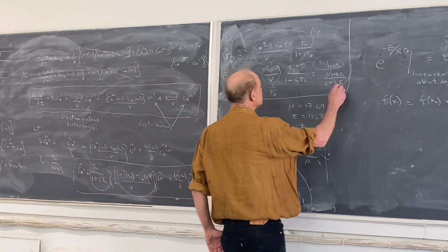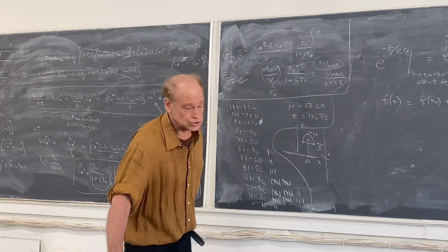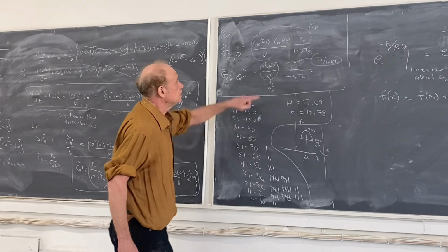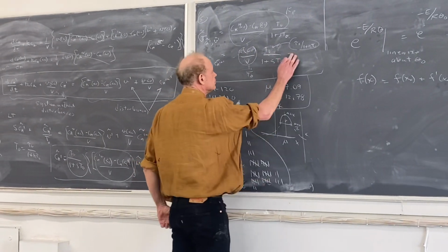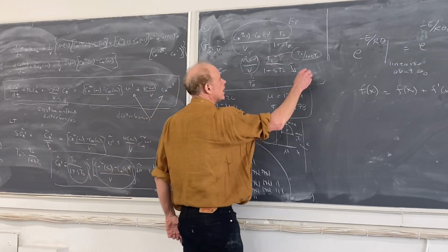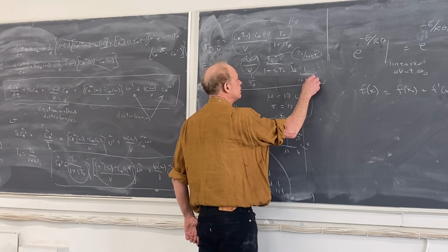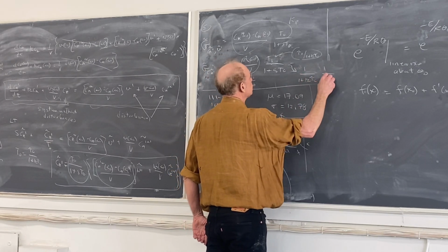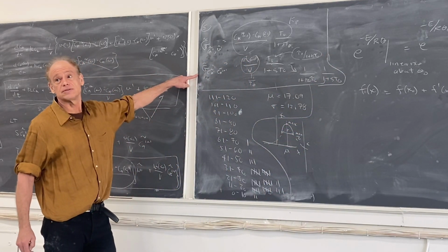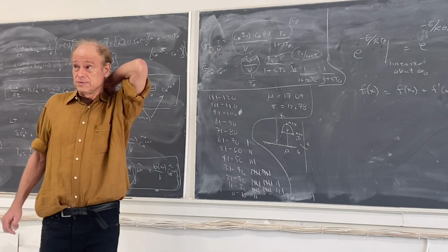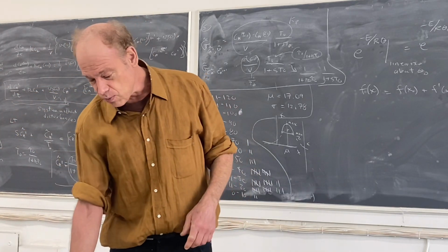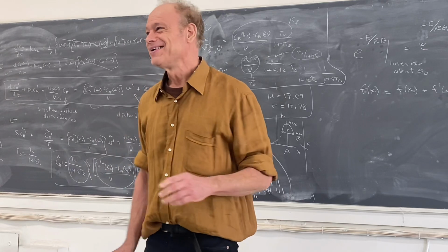So if I write this correctly, let's just do the steps now. Tau 0 is tau over 1 plus k tau. So when I plug in here, I divide by tau 0, that cancels the tau 0. And what I'm left with is 1 over 1 plus k tau times 1 over 1 plus s tau 0. So that's what this transfer function is. Questions? So that's just fixing the error from last time. What happens when I try to write just one more equation as the hour is over?